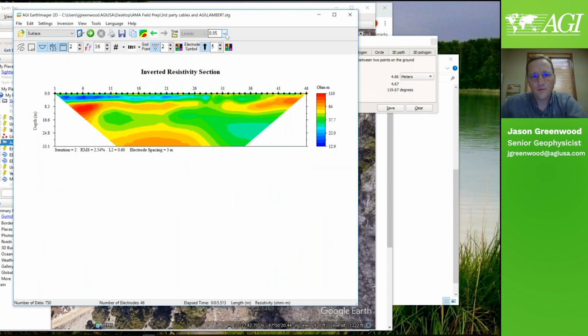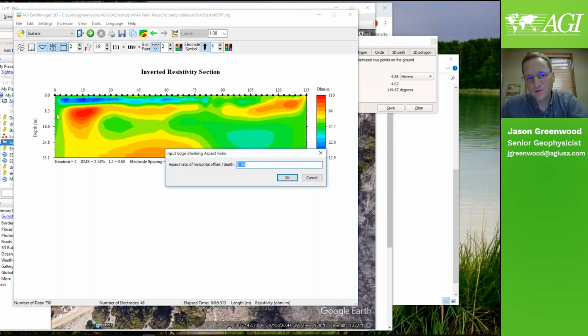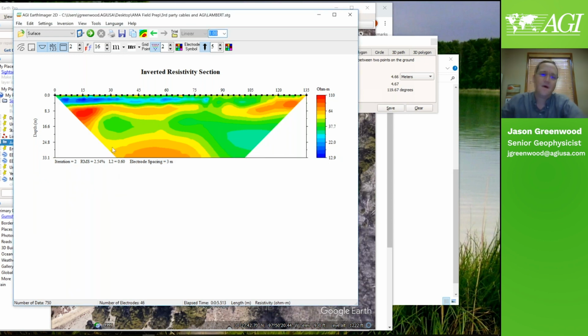One common way to look at these is at 1-to-1 ratio in the unit you're interested in. This is probably, okay, so they're running in meters because I can see 9.84 feet, 3 meters. And then you need this clipping boundary, about a 45-degree angle is common. Without topography, a 1 will give you that. See, there's no resolution here. We don't want to show this portion of the model space. That's not a real target, and this as well. So that's why that's clipped off.